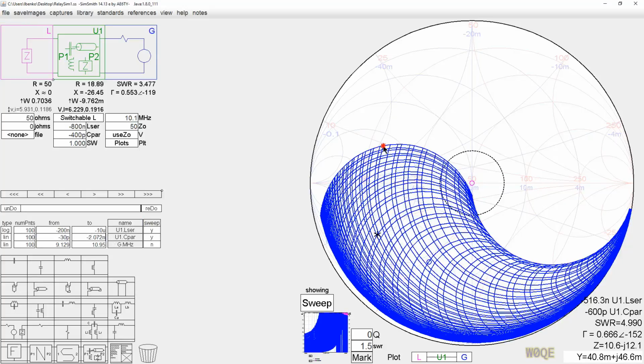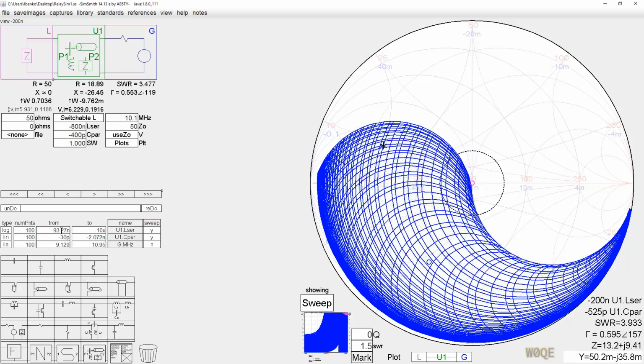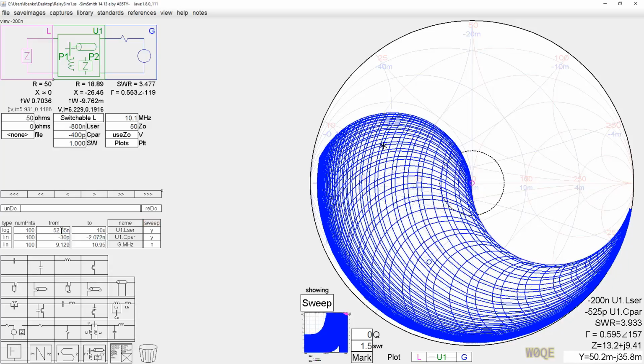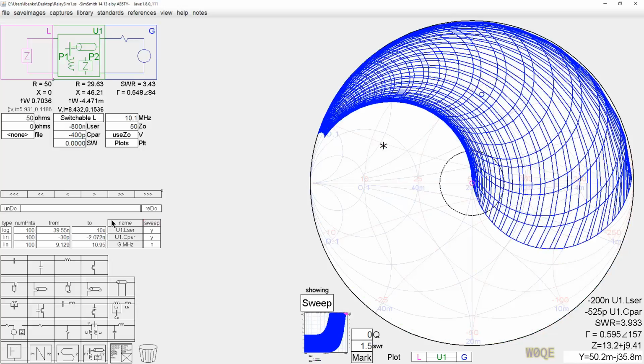And then up here, what's the problem? The problem is at 200 nanohenries. Well, that's a little bit of a problem. It's hard to get the inductance to be just arbitrarily low, but let's assume we have a really, really good inductor and we can get it down to, say, 40 nanohenries. So that's the range that circuit would work over. And here's the range the other circuit works over.